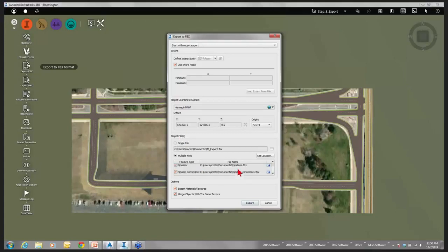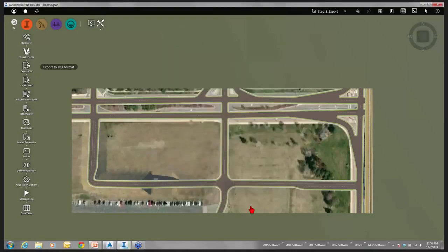And I can see the pipelines, the pipes, and the buildings and the grounds. In my previous slide, you saw the slide about the pipe networks. I actually added some storm networks into my model so you could actually see it. And then it's just say IMX export, the location. We'll go single file back and set the location, and you say export. There we go. It exported out a lot quicker than the IMX. File size was a lot smaller.